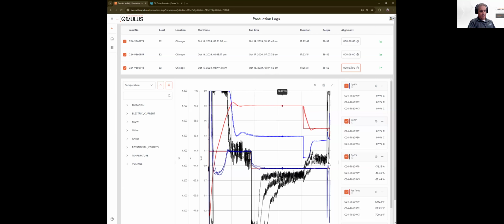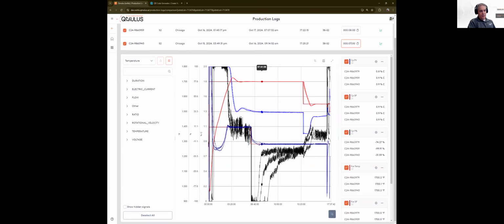And already I could see here, if you look at these black lines, this is my power. And I could see how the 3 jobs took significantly different power, or significantly is also subjective, right? But they took different power, and I get to see this as troubleshooting that, okay, there was a difference, even though the carbon set point and the temperature set point pretty much line up nicely. There's a difference in reaching. So surface area or weight definitely was different in all 3.